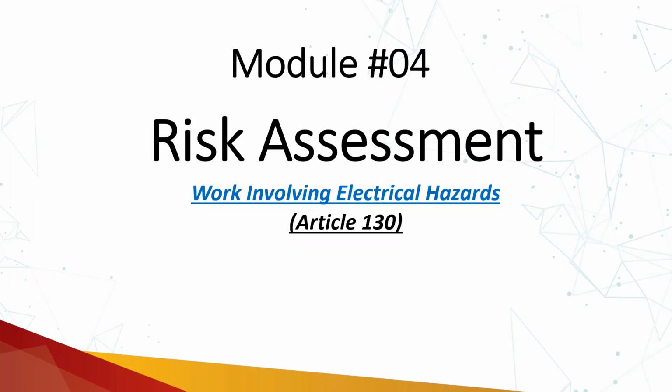Also, if you have been given a task to establish an electrically safe work condition, the act of establishing an electrically safe work condition is considered as a justified and authorized work. A risk assessment is also required. Once an electrically safe work condition is created, then further you are not required to wear any electrical personal protective equipment or arc flash PPE.